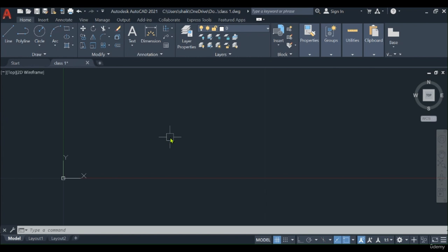Once they approach the architects, the architects will go through the site plan: what is the area, what are the directions, what are the undulations of the ground, what are the levels, what is the terrain, and what obstacles are there on the ground. Everything will be surveyed by the architect. Once the client visits, the architect will do the survey of the particular site. They will take the different levels, the boundaries, the directions, the road width, and whatever objects and obstacles there are, everything will be taken by the architects first on the ground.